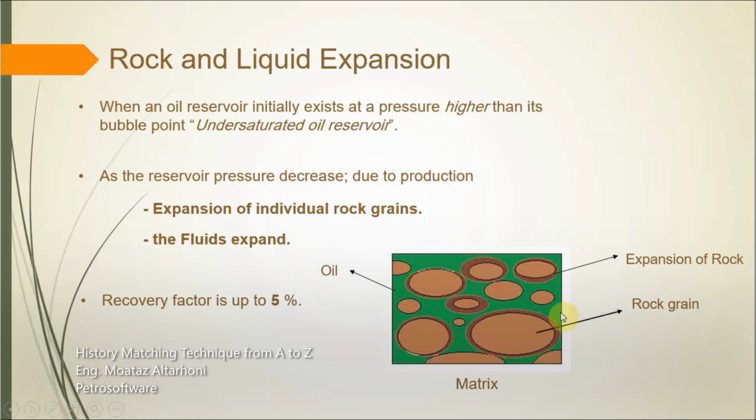acts as a tank with constant pore volume, so the rock in the first case does not change and has no expansion. So the difference between the expansion and the initial point must be equal to production. So here in the first case, instead of this expansion of rock, the material balance would fill it with oil. So any expansion of rock depends on the rock compressibility and how much volume of water is initially in